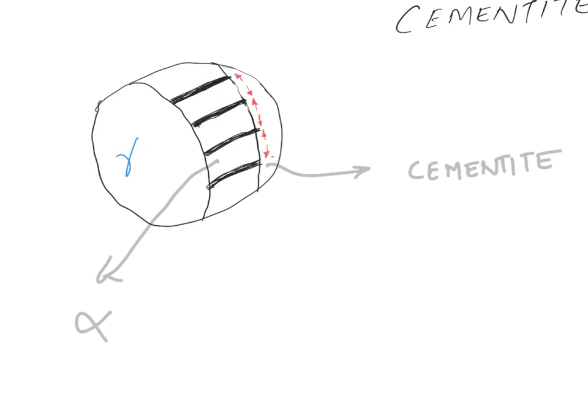the one reason for pearlite to assume a layered structure is that the carbon atoms diffuse only over minimal distances. So that's yet another reason. In pearlite itself, we have two variants: coarse pearlite and fine pearlite, which will be discussed when we start talking about isothermal transformation diagrams.